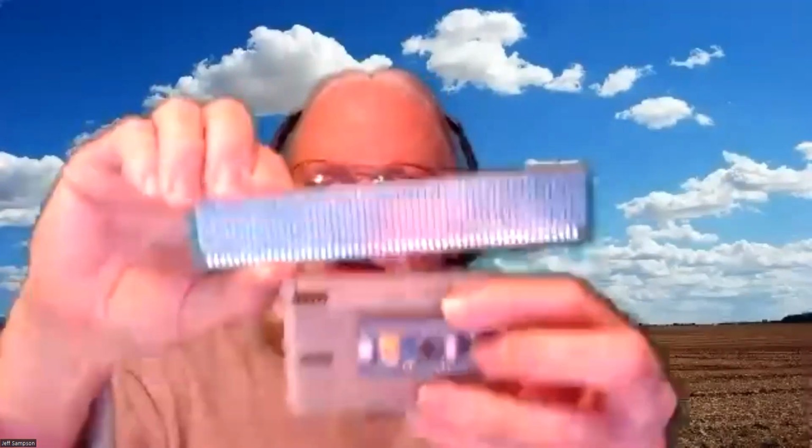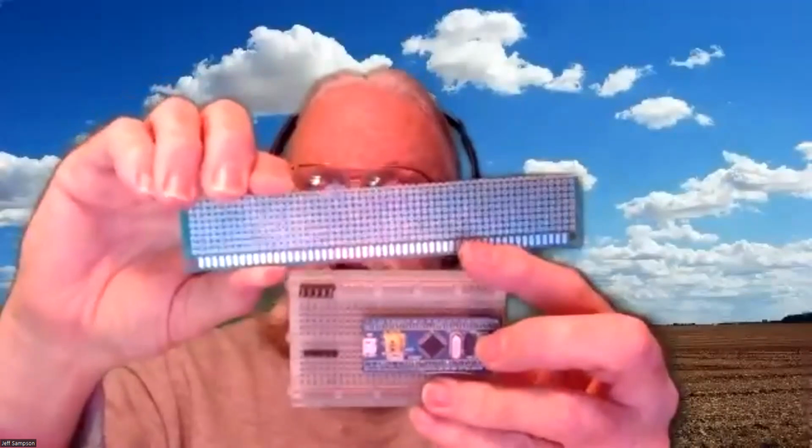Another way would be to actually get a perf board and solder some socket strips down, and then plug the board into that, and then solder down your header pins for everything you want to plug in. Then you just hardwire everything: flip the board over, and on the back of the board, put all your wires to hardwire everything. And one other option I came up with was to plug it into a plug-in proto board, and then grab a random board like this and solder header pins on here to use for connectors, and then solder stiff wire from all those. You take those and just plug them into wherever you need on your board. So that'd be another way to do that. I'm just trying to figure out what's a quick way that's going to be flexible enough that I don't waste a lot of time on it.